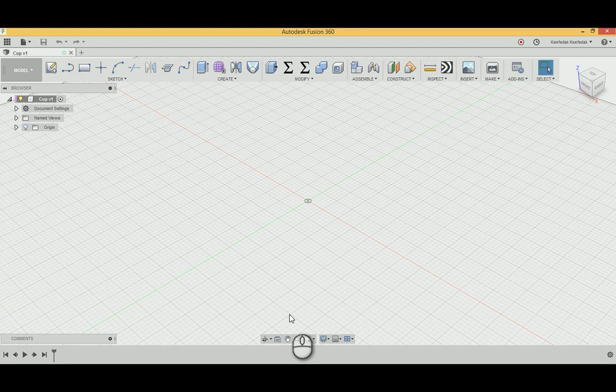I'm going to do it as a loft, because loft is really cool. So this is what we're going to do. We're going to create a circle, and then we're going to create another. Remember I told you we can create more than one sketch plane. We're going to create a sketch plane up here, create another circle, then loft from that circle to here. It'll be right on the money. It'll be a solid. We'll shell it out.